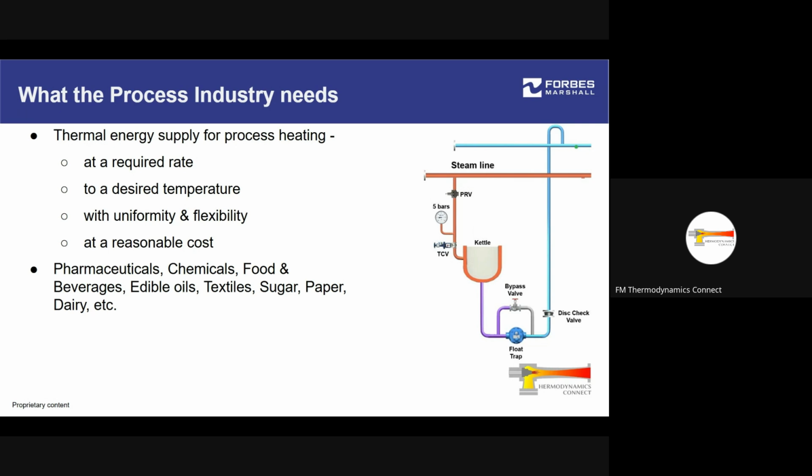It will be controlled. The opening will be closed to a certain extent, and the flow rate will be reduced. And correspondingly, you will get a reduction in steam flow rate and resulting in a reduction in heating rate as well. But the funny thing is, when steam enters into this jacket, the only amount of heat it can deliver to the process is the latent heat associated with phase change. So steam comes in as saturated steam, ideally, but in most cases, it will be some form of moisture contained within the steam flow.